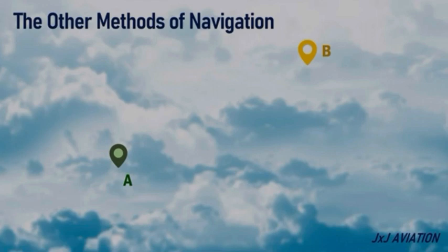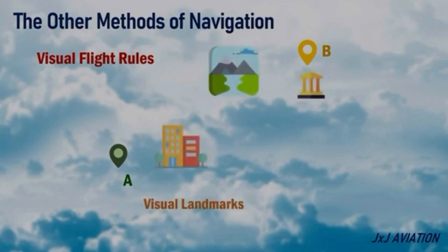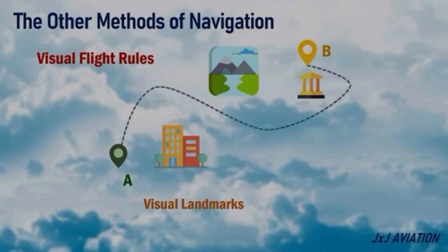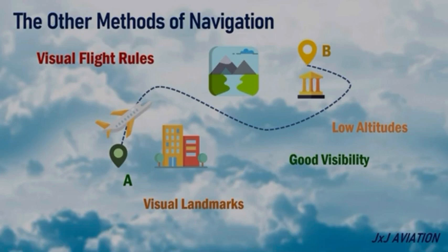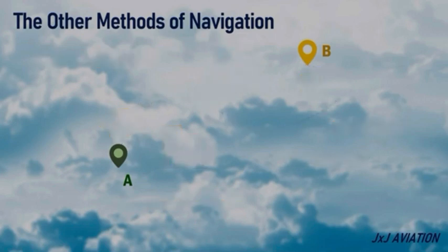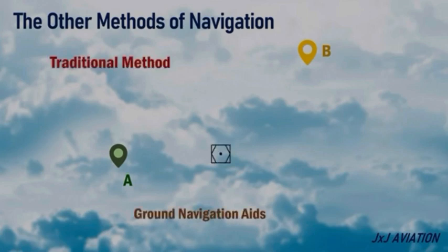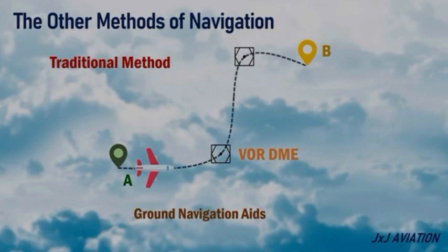We do not need any sensors like the VOR, like the NDB on the ground, unless all the navigation has failed and we cannot operate, or the performance of our navigation equipment on board the aircraft degrades. So in this case we shift back from area navigation to the basics of navigation, as long as we have some NAVAIDs available on the ground. But mainly we are tied to the NAVAIDs in space, which are the GPS or the GNSS.